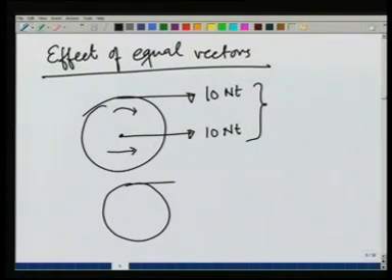On the other hand, think of the same wheel, if there is a rope pulling it which is tied to its end, whether I apply a force here, here or here along the line of action, its effect would be the same. I can also hit the disc from this side by the same force, and that would also produce the same effect.